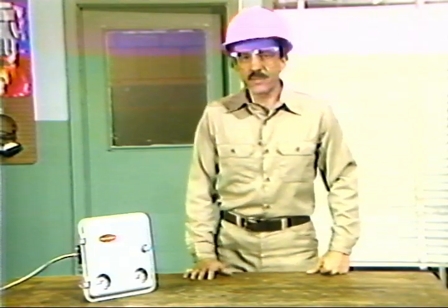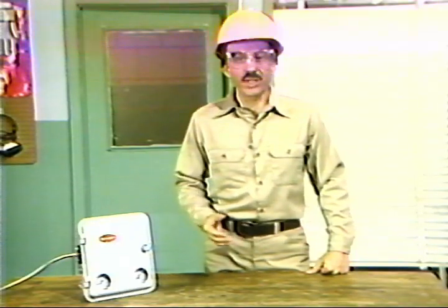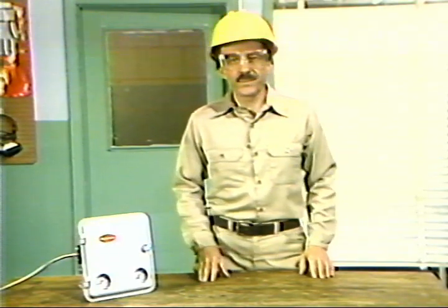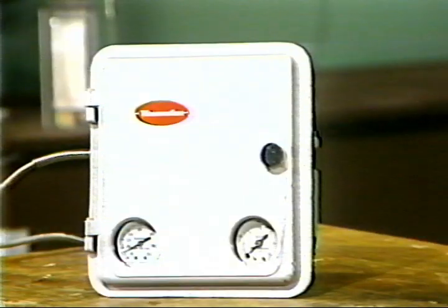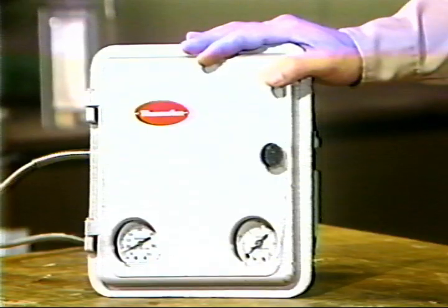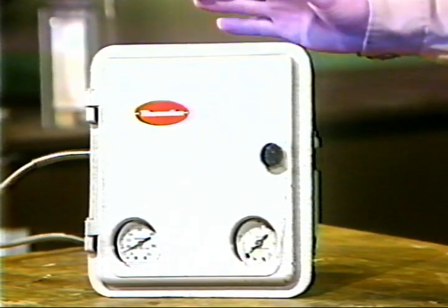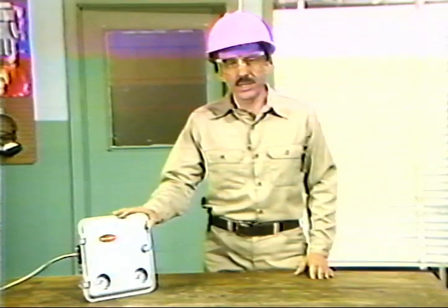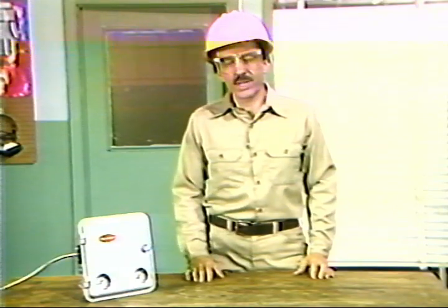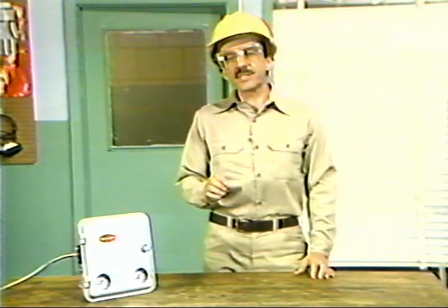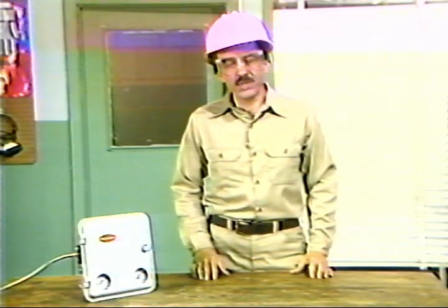In this program, we'll identify how these basic mechanisms are utilized so that the controller measures the input signal, compares it to set point, computes the difference, and generates a corrective output signal. Now, in a proportional controller, the basic mechanisms work together to enable the controller to produce an output that is proportional to its input. We'll examine how this controller provides P-only control in a few minutes. First, let's see how the controller's basic mechanisms can be arranged so that it can provide P-only control.